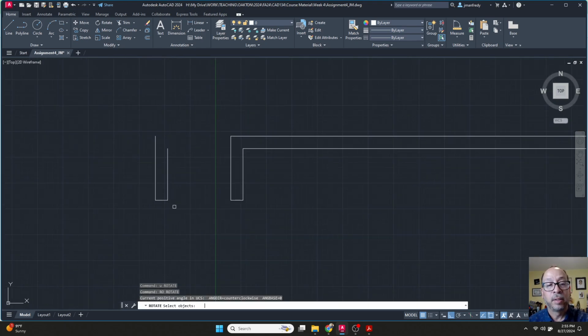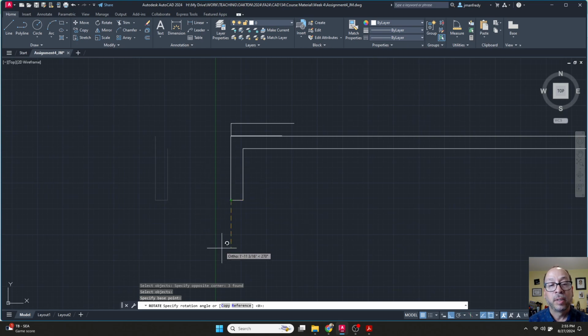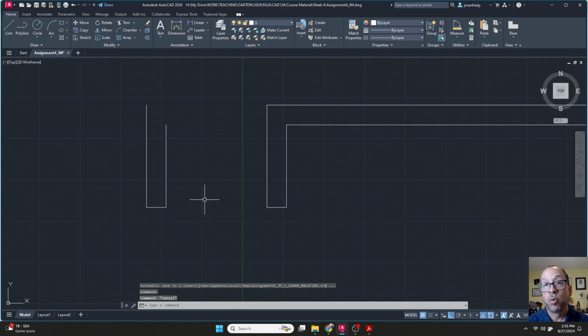Now, you don't have to choose a rotation on the object. I can type rotate, enter, click this object, and rotate it from way over here. Click. That becomes the center of rotation. Now, when I rotate, you'll see here, if I move my mouse left, right, top, and bottom, again, with ortho turned on, or F8 on your keyboard, it will rotate it around this location. Escape. So the center of rotation is very, very important when you do rotations. I'm going to delete this.